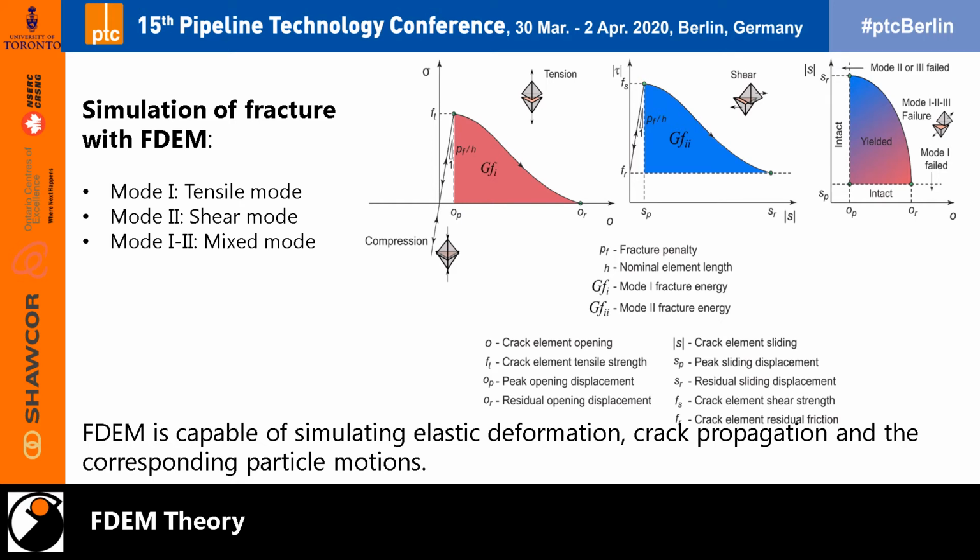Another method we examined is FDEM. FDEM stands for Finite Discrete Element Method. FDEM is an explicit method that can simulate from the meso to the macroscopic scales in 2D and 3D. Interaction and forces transfer between the elements are governed by penalty values, which cause stress and deformation in tetrahedra that can cause yielding and failure in cohesive crack elements.